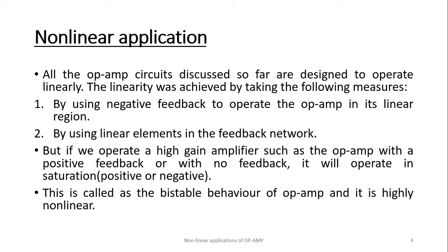But if we operate a high gain amplifier such as an op-amp with positive feedback or with no feedback, it will operate in saturation, positive or negative side. This is called the bistable behavior of the op-amp, and it is highly non-linear.